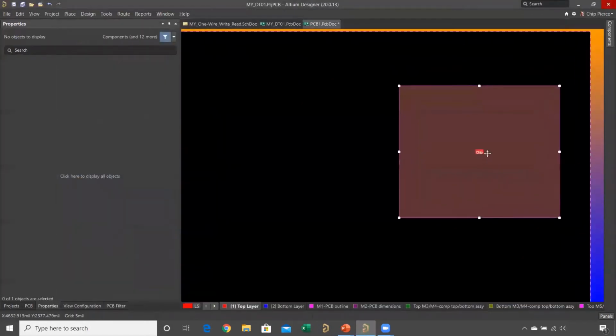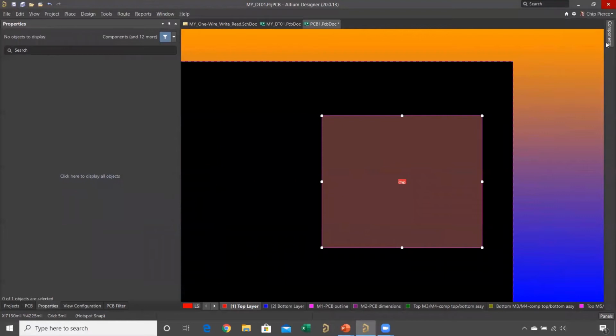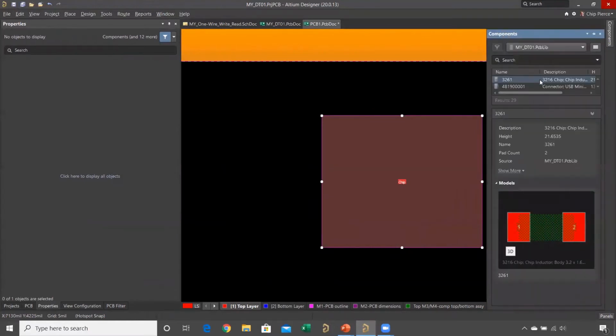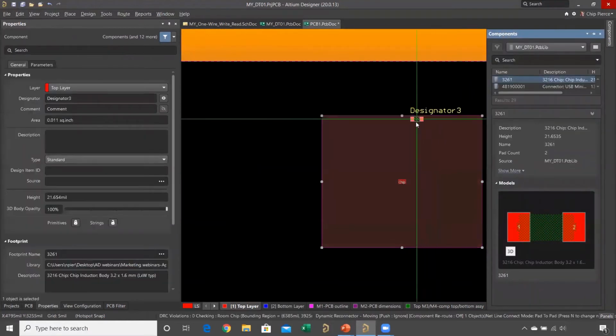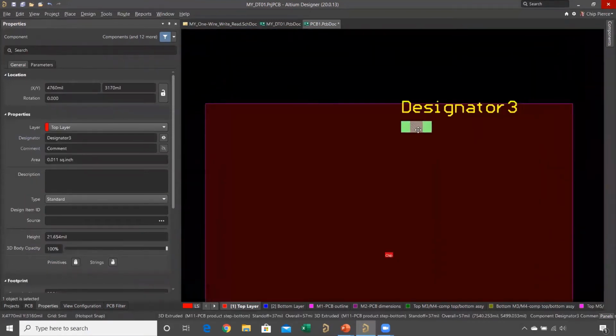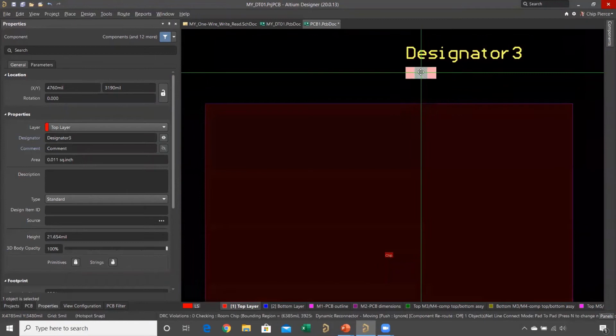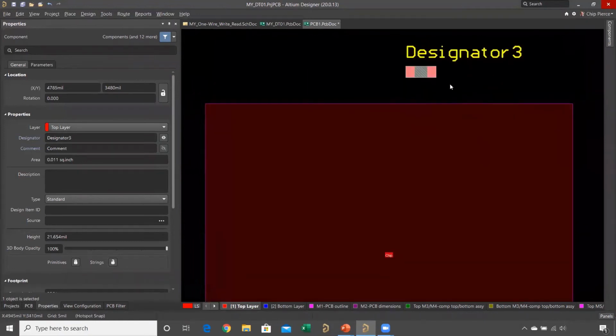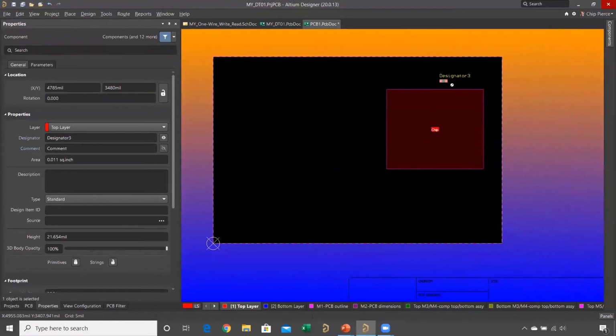You see the room just inherited that name right there. And now if I went to place a footprint down in that room, it's going to bark at me right there. You see that? It's saying, sorry, pal, you can't go in that room. You've got to stay out. And I've got online DRC enabled, which is doing live design rule checking.